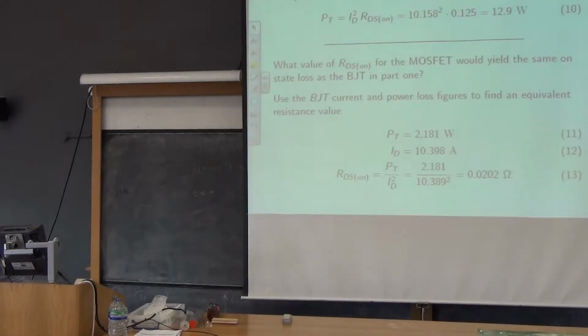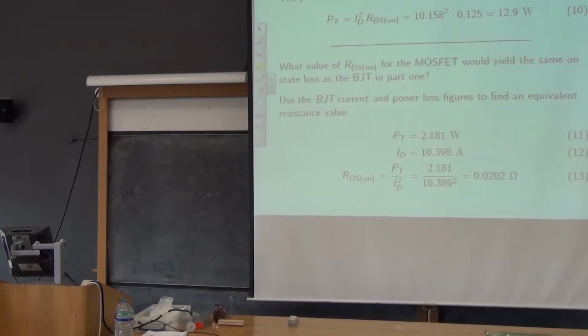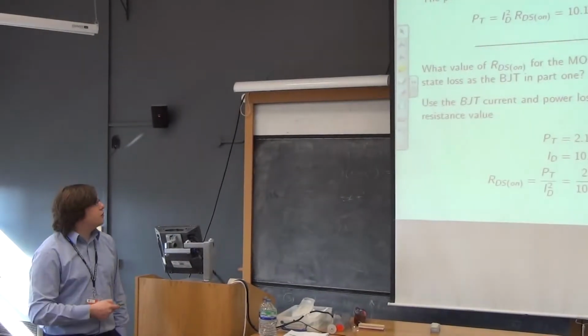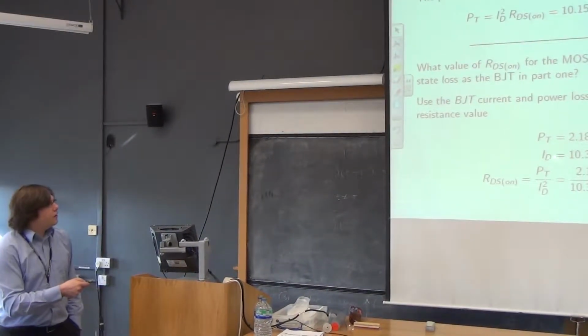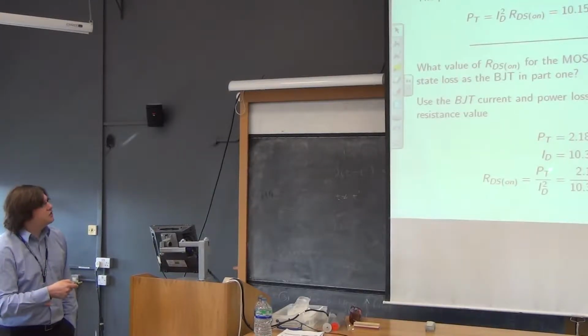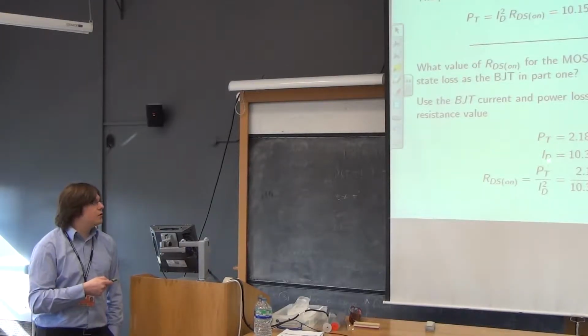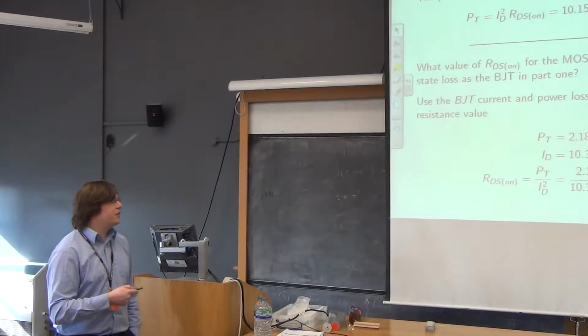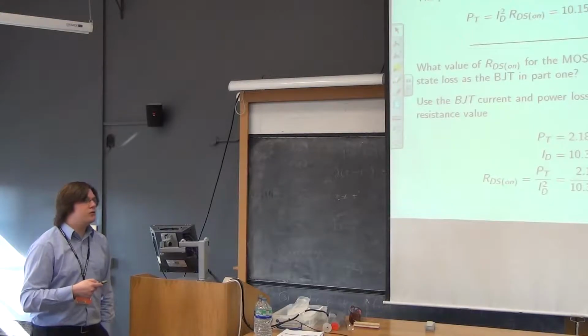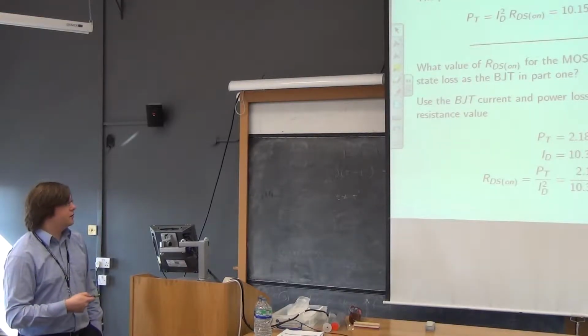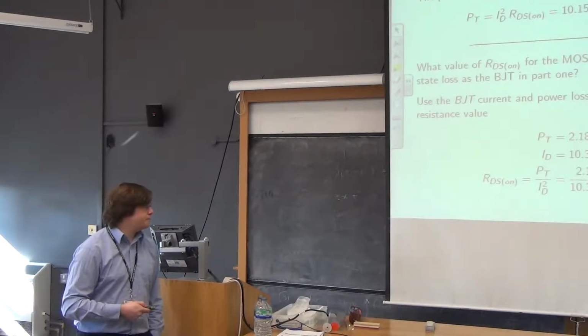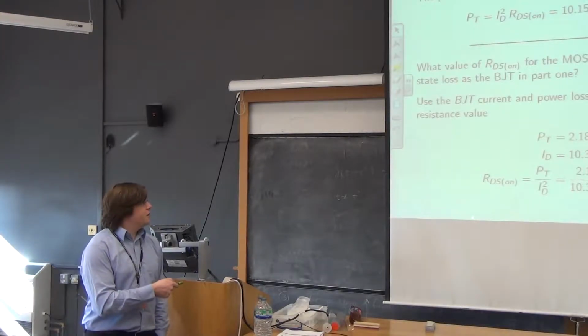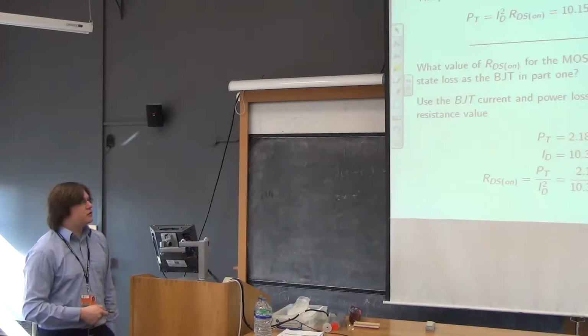I did. So, for the bipolar transistor we had 2.2 watts more or less, and okay, it's IC for the bipolar transistor, but since this is still a FET we're talking about, it's ID. But this number is the bipolar transistor number for drain current. And we can say, well, we need a value for R, so we can do power upon I squared.